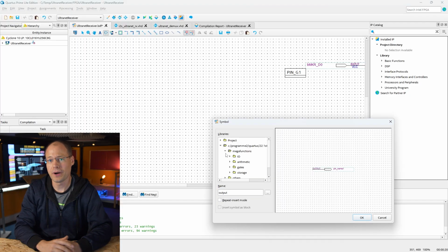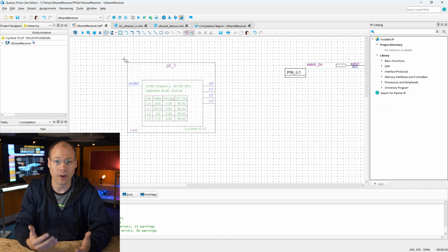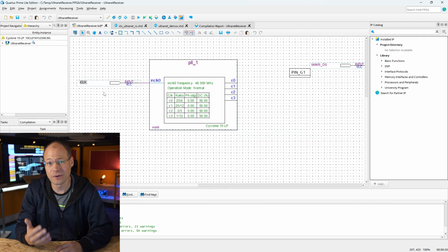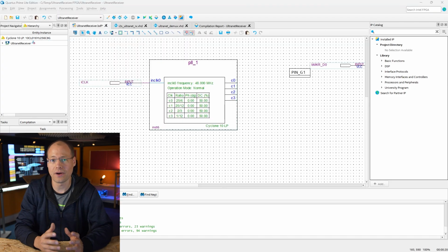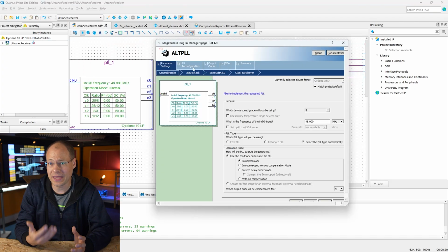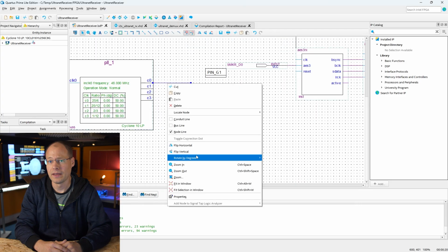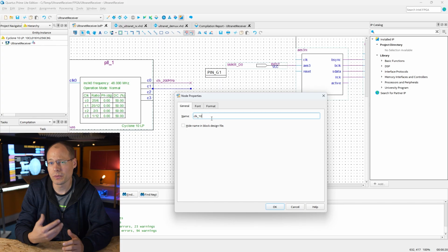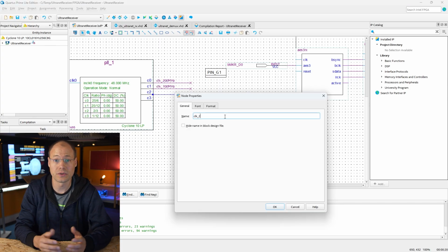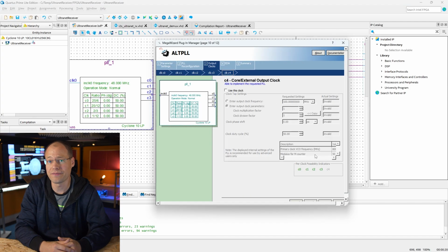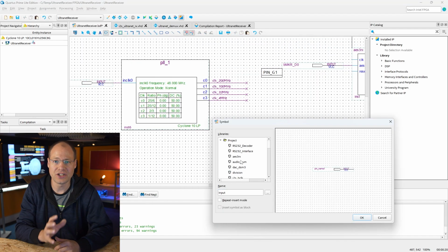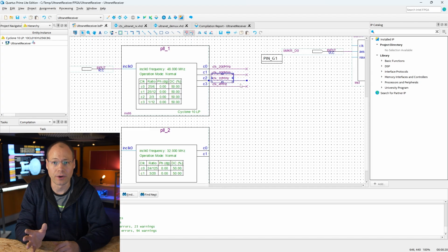For everything to work properly, we still need to provide the individual logic blocks with a suitable clock. The input blocks must be clocked with a considerably higher clock rate so that the bit edges of the digital signals to be read can be detected reliably. The microcontroller gives us 48 MHz as a base clock, which we can rise up to 100 MHz or more via a so-called phase lock loop, or PLL. We only have to distribute this HF clock to the individual receive blocks.